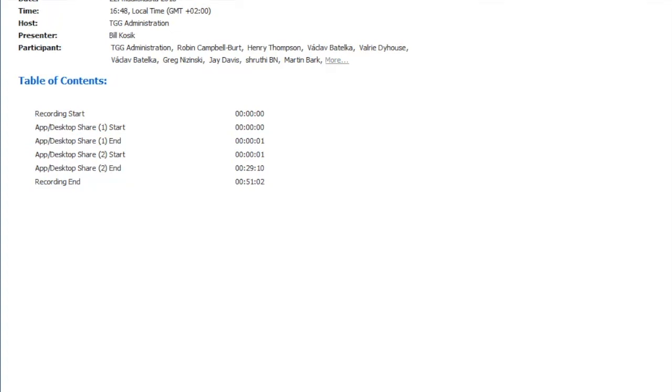Okay. This is an interesting question here. In a comparison, would a new data center with 100% liquid cooling require 3 times the amount of space? From my point, I'm assuming, Bill, that would depend a little bit on the type of liquid cooling employed. Is that right? Yeah, there's a couple aspects to that. If there's a 1-to-1 correlation, where the server for the air-cooled will be the exact same power and size as the water-cooled, there'll be no difference in the data center size.